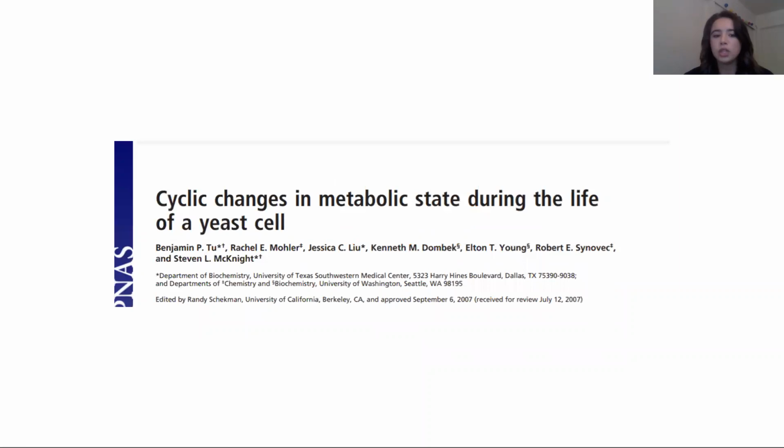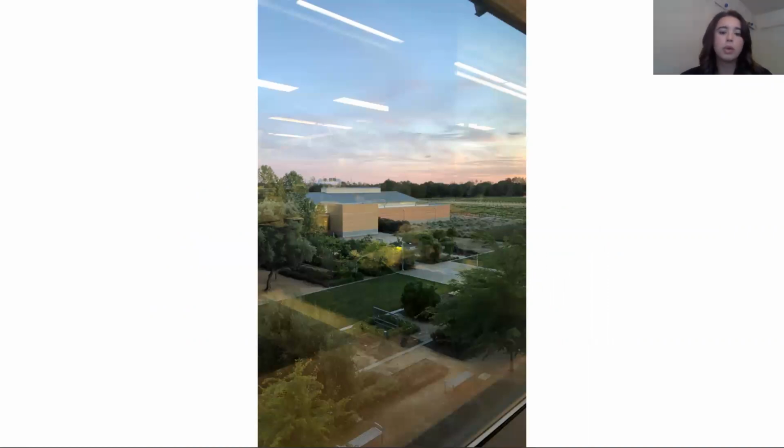Some literature points to the existence of a circadian rhythm in yeast metabolism. This was an initial thought or explanation, but after seeing this in both my and my colleagues' experiments, we saw that the waves were greatly reduced by blocking the light from the bioreactors that was coming from the big, beautiful windows in the RMI building. So this led us to believe that there was a technical issue and a sunlight component that influenced these redox readings. You'll see in the nitrogen data, which I'll show later, that the curve is much smoother, and earlier runs will have these kind of undulations.